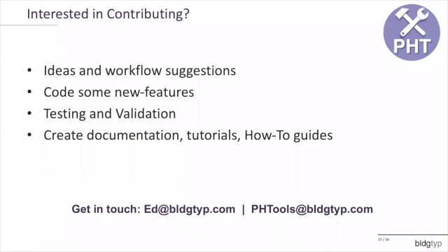And then I was going to ask if you dealt with the output, like, can you manage the output variables for Energy Plus directly? Yeah. Cool. Yeah, that's a good question. There's a bunch of native Honeybee tools that allow you to manage that. We've also written a couple of presets, where you can say, I'm really interested in, I have one that I use for peak load assessment, where I want to do an Energy Plus model and I'm not really interested in annual energy today. What I really want to do is focus on peak load assessment for cooling.